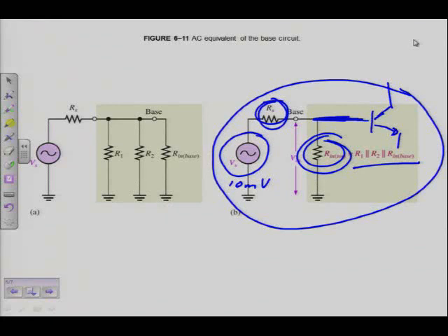Okay. Alright, so that is what is explained there on page 266, just below figure 6.11. As you can see in the figure, the source voltage is divided down by RS, the source resistance, and R in total, so that the signal voltage at the base of the transistor is found by this formula. Remember, lowercase letters are AC voltages, so v small b is equal to R in total.